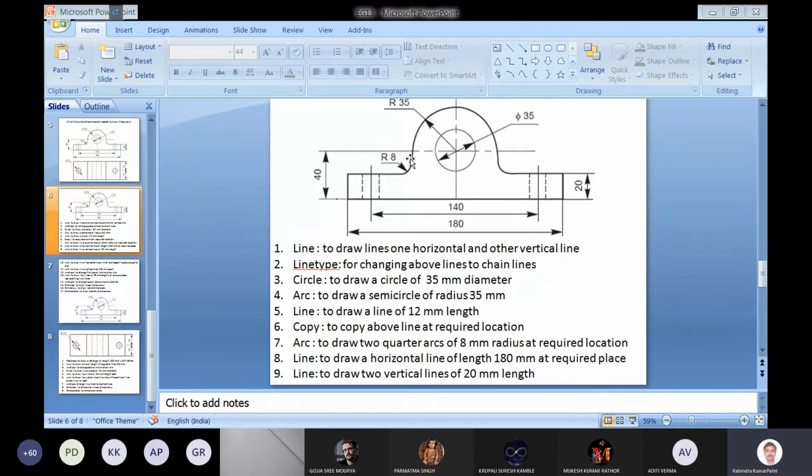Again we can identify another end point by drawing this line and this line and this line. The length of the line also can be calculated for this case. So this point we can locate, this point we can locate, and the radius of this arc is given. So we have three parameters. By using these three, we can draw the arc. Here also similarly we have to draw this line, and after that we can draw the arc.